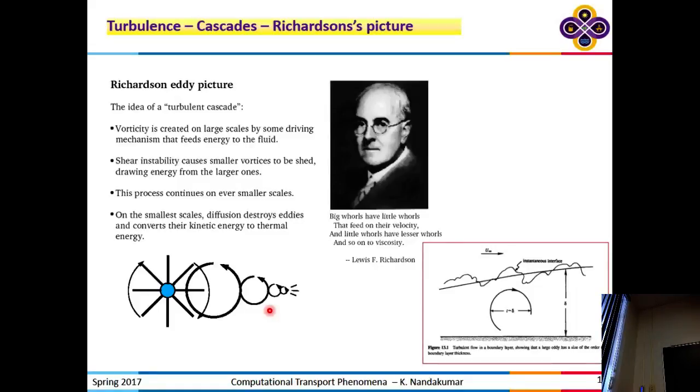And the dispersion is done by small-scale fluctuations that make the particle homogeneous locally. Okay? The distributive takes it and distributes it everywhere in the vessel, and the dispersive mechanism breaks it up into tiny particles or droplets to create the homogenization.